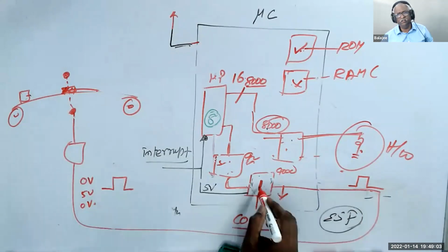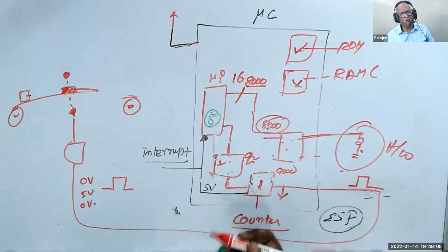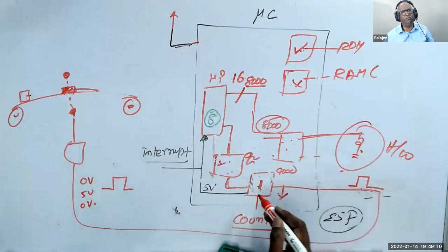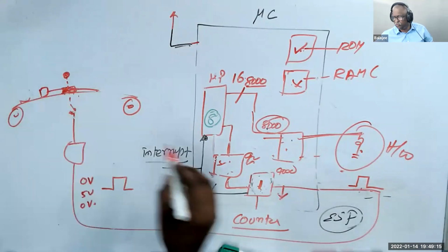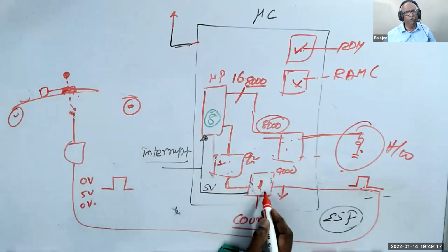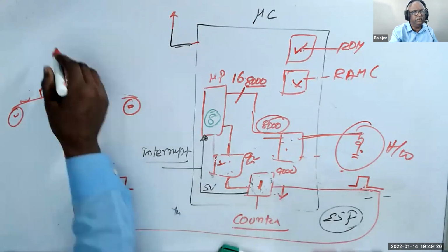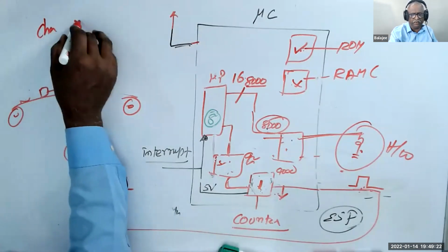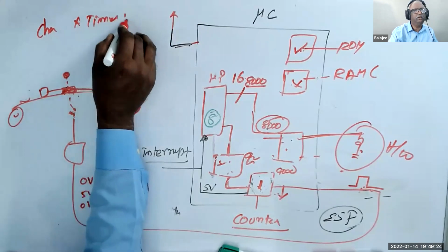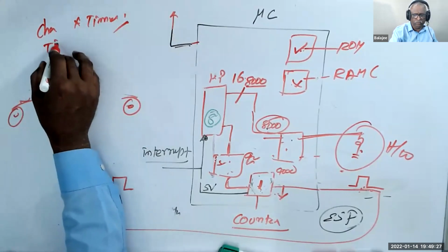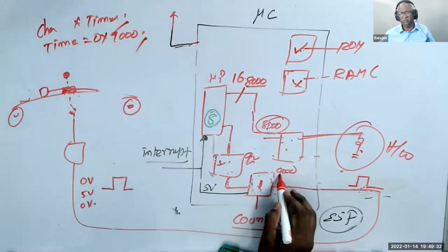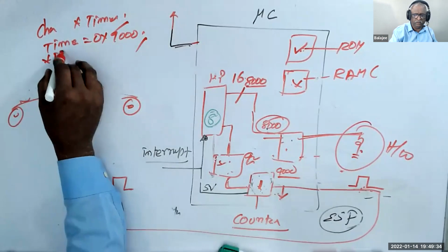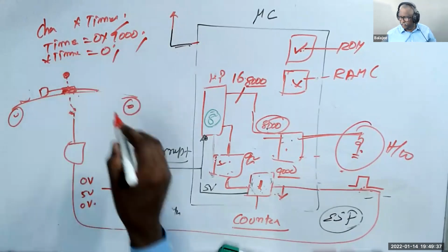Now this guy will count. The same timer will count, but instead of counting a clock, now he'll be counting the pulse. Now it becomes 1. Now one more object has come, the second object, it becomes 2. So whenever you go and read, you will know how many. So if you say char start timer equals 0x9000, that is the address, you initialize it with 0.